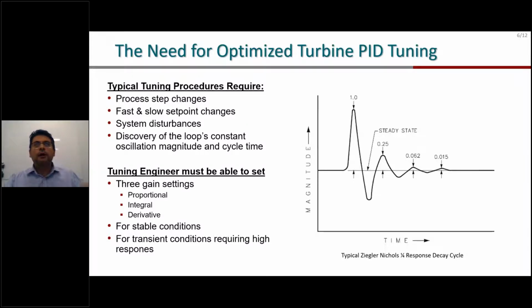We talked a little bit about multi-loops and PIDs, where each PID is trying to communicate with the other PID. That was in the previous slides. All these parameters have to be considered when you are tuning your turbine. And in some cases, I'm not able to take it to the maximum conditions. To tune it, you sometimes need to take the turbine to instability so that you see the maximum range that you can take your turbine to. Sometimes on site, you cannot reach that level. So you always have to have that experience. It takes years of experience, but it's what we do every day.